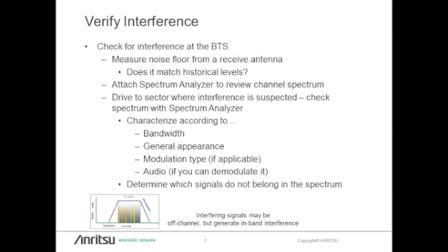And this is applicable, particularly in border situations where you may have other, say LTE or WCDMA signals, and you can actually identify the modulation. I've been on a lot of hunts in Southern California, for example, between the border of the U.S. and Mexico, or also a border with Canada, where you may have other cell systems, different operators in different countries, that may be touching on the frequencies in which you're operating. So that's a good way to identify the type of interference and generally where it's coming from.